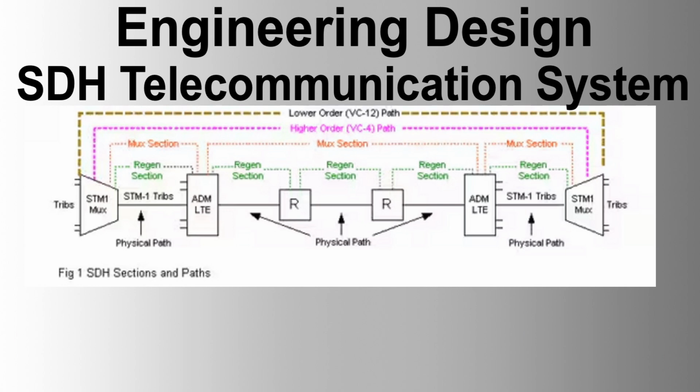Time synchronization. GPS-based synchronization. GPS-based system synchronization, primary reference clocks, PRC, and timing distribution units shall be provided and integrated into the SDH system. Clock input-output should comply with G.703, and multiplexer OLTs must be able to receive time synchronization signals from external sources and pass timing to outgoing lines and tributaries.